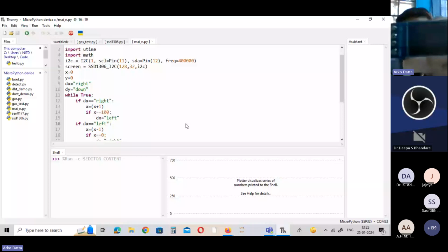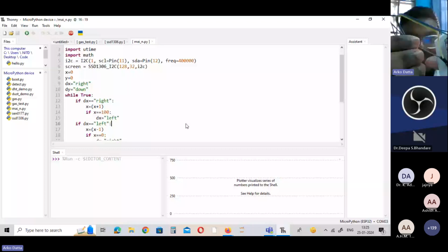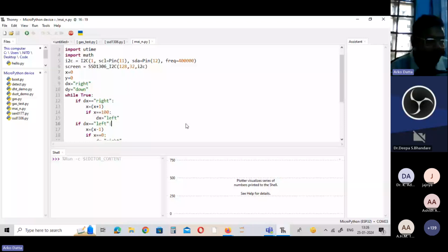Yes, it is visible. Okay, so we learned another thing from this, which is that the cable quality should be checked. These are some thicker cables which we procured. After using these thicker jumper wires, we are able to use this. So sometimes the issue may not be with the software. Sometimes the issue may be with the hardware also. So we must check our connections and everything.